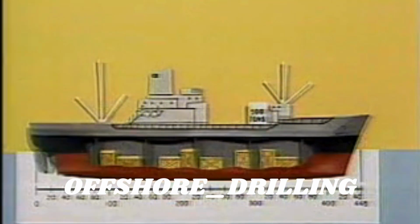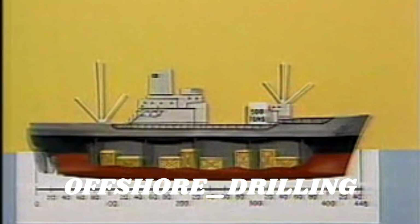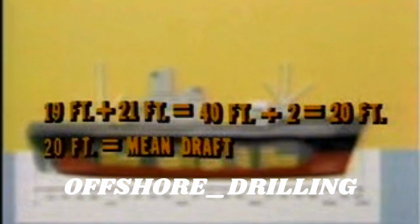Take a vessel with drafts of 21 feet forward and 19 feet aft. The average of these two drafts is the mean draft. It is 19 feet plus 21 feet divided by 2, which equals 20 feet. So 20 feet is the mean draft, which we use to enter the deadweight scale or hydrostatic curves to obtain